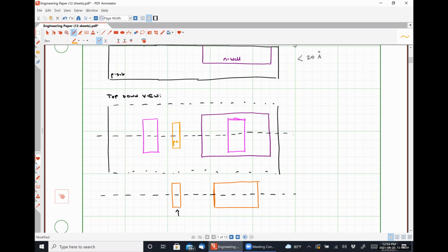So when we have metal semiconductor junctions, we have two options, all right? One option is forming an ohmic contact, and that's exactly what it sounds like. It just allows electricity to pass through very easily. And then the other option is what's called the Schottky diode. A Schottky diode is a metal semiconductor junction. So it's like a PN junction, except that instead of having semiconductor material on both sides, one side is metal. And so it's still a one-way diode where there's effectively an infinite amount of electrons on one side of the junction.